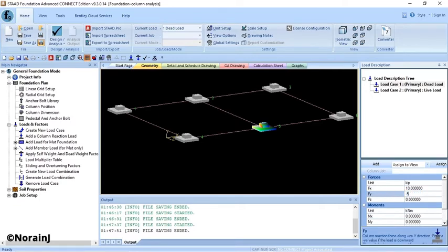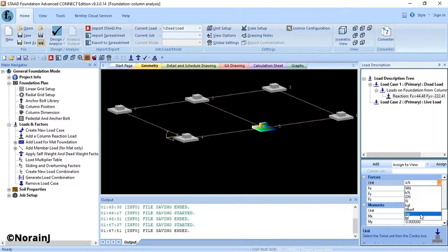And then click add. For the second direction, we still use kip for the unit, and for FX is 10, and for the FY is negative 200. And then click at other place to ensure the value is added and click add.